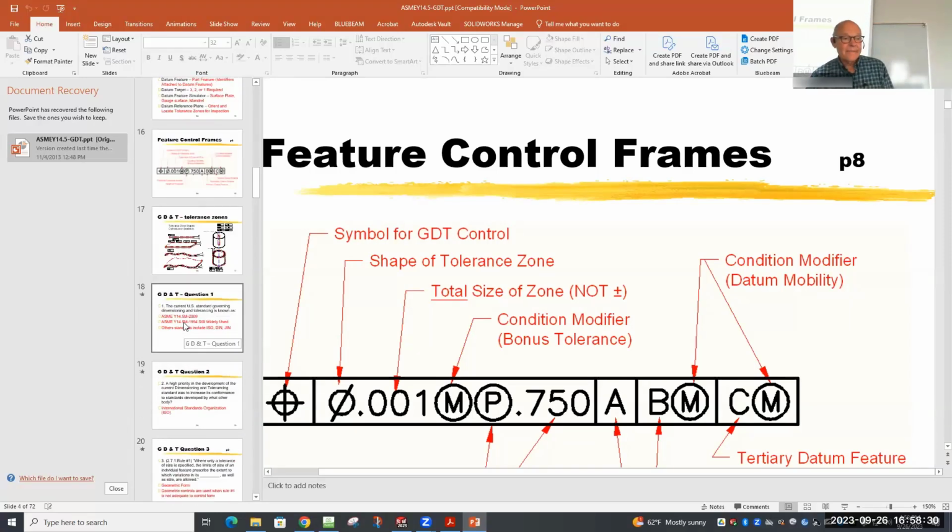Well, I'll just tell you, you've got an angle, right? So you're off by half a degree. The further away you get from the apex of that angle, the further off you are. So if you get an angularity control, the length of the surface determines what you're actually controlling, which means you don't really know what you're controlling.